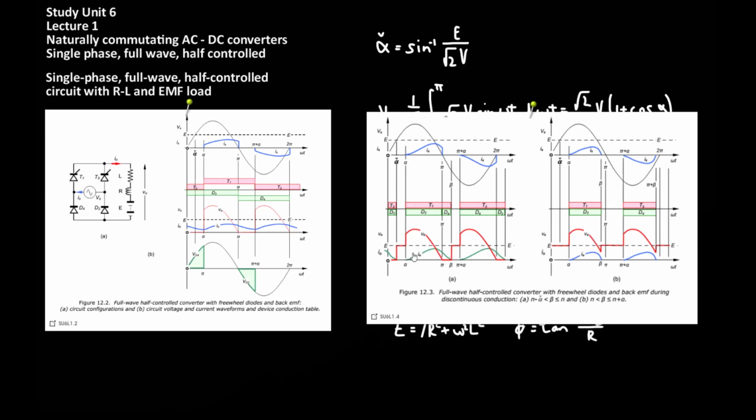In the second case, because there's not this added complexity of the current being driven to zero during freewheeling, the switching pattern is much simpler and follows more closely the continuous pattern. Of course, in this mode, it is different to the previous mode because there is now no current conduction at all, not even a decreasing value, between the conducting parts of the cycle.